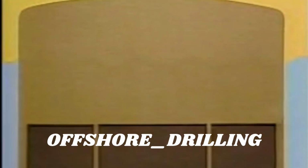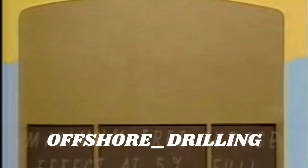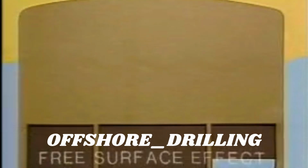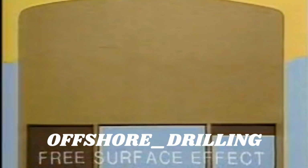When the tank is empty, there is, of course, no free surface effect. Once you start to fill the tank, the free surface effect increases rapidly with the first few tons introduced and is nearly at its maximum value when the tank is about 5% full. It remains close to the maximum value until the tank is 95% full. Then it returns rapidly to zero for a full tank.